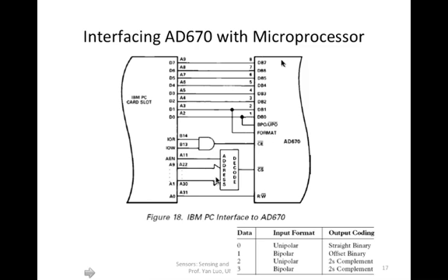The other pins, for example, I'll write coming from the microprocessor system and putting into an OR gate and to this chip enable. That means either a read or write operation will make this a 0. I think we're missing the bar here. Okay.